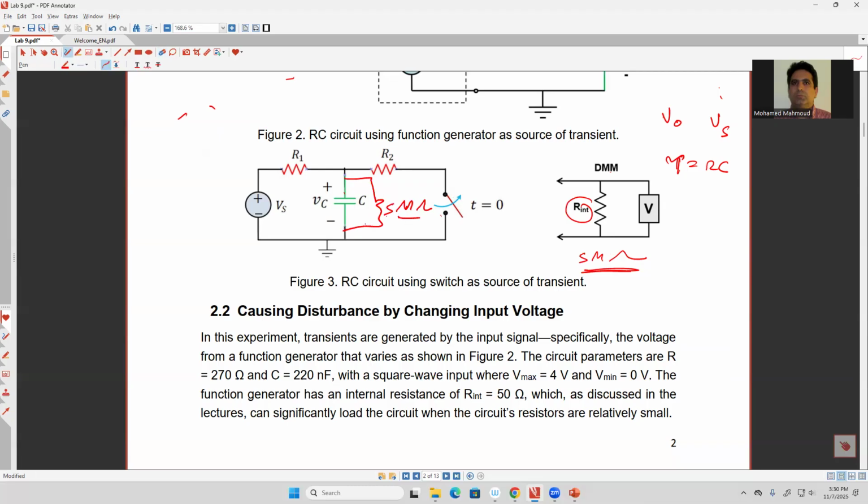However, if you can make R1 and R2 in the range of 100, because R2 has to be smaller than R1, so if I can make R1 in the range of 100, 200, something like that, then 5 mega ohm may not have impact, and I can safely ignore it. The calculated result will always have some error, but it is going to be a very small error, and should be accurate enough. So this is one case.